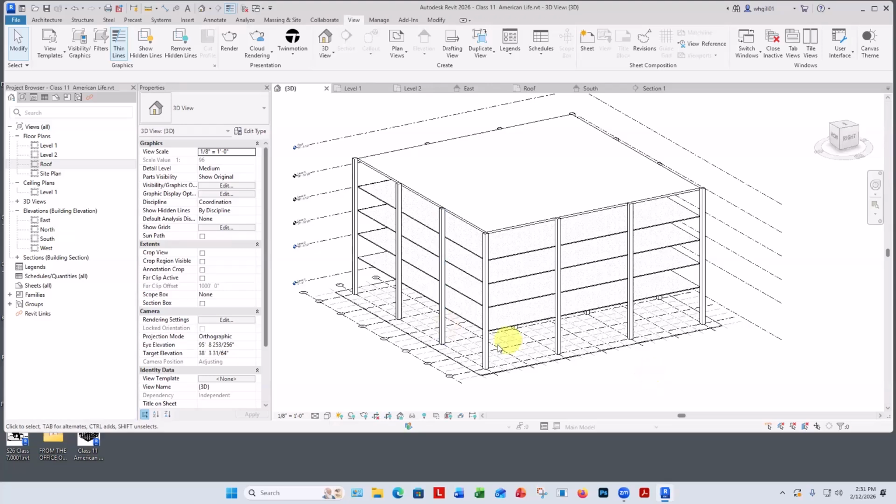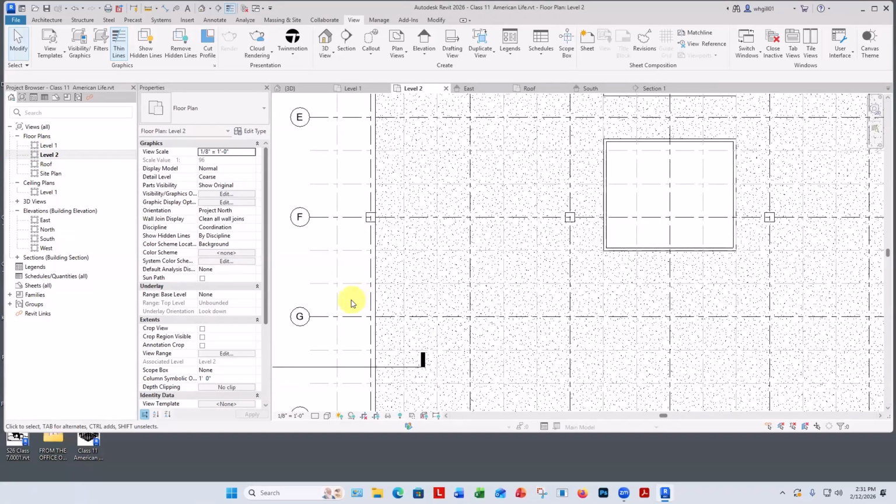I'm going to leave the plaza level curtain wall for another day, but do want to get the walls and glazing in on the upper floors. It basically starts at the second floor, or a bit below the second floor, and goes up to the roof. So we'll create a new 24-inch wide wall that will form the spandrels between the sections of glazing. In reality, these are basically sleeves to cover the structural steel beams inside.